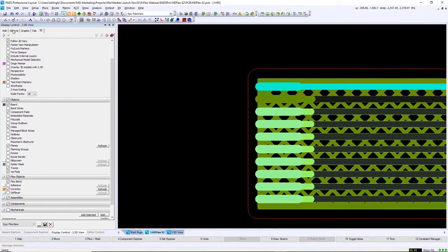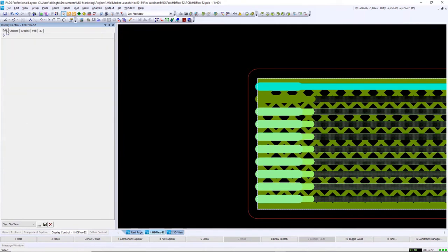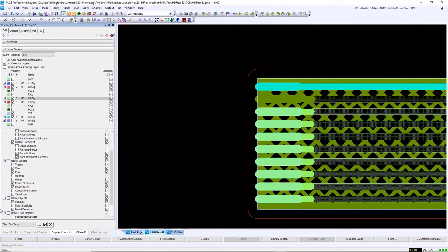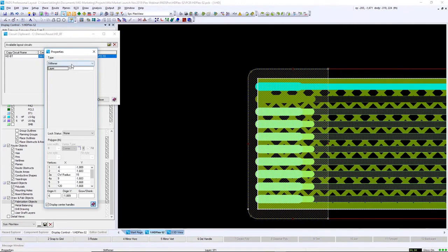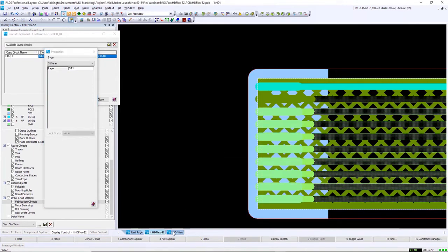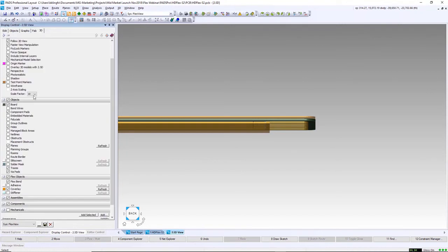And two, if the flex bends in that area, it can prevent cracking where the traces route into the actual edge fingers. So as you can see, the stiffener is just a draw object that's placed on the stiffener layer that we defined in the stackup. Because this drawing's been placed on a layer that's been tagged as the stiffener, when we move over to the 3D view and check the box for display stiffener, it will then appear on the flex.